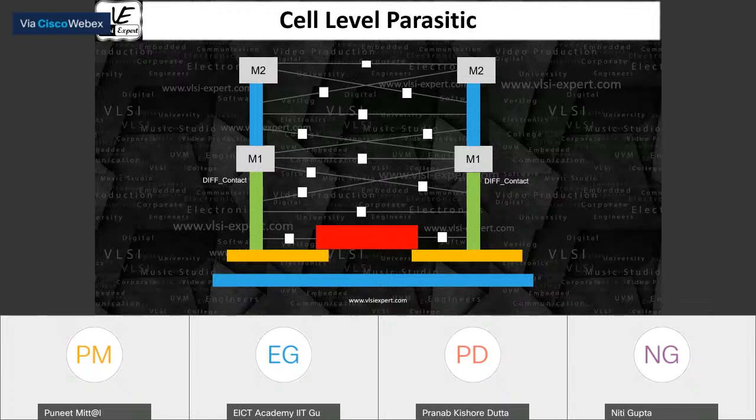When the tool is going to calculate the timing or the delay, it will consider the .lib file. In that .lib file, there is an input cap and an output cap. It will consider that input and output cap, and on the basis of that, it is going to calculate and do the simulation. This cell level extraction you will see in the SDF file. Device level extraction, which we do on the device level side, is also present in the SDF file. That device level information comes from the netlist, and that netlist is going to give you that information.